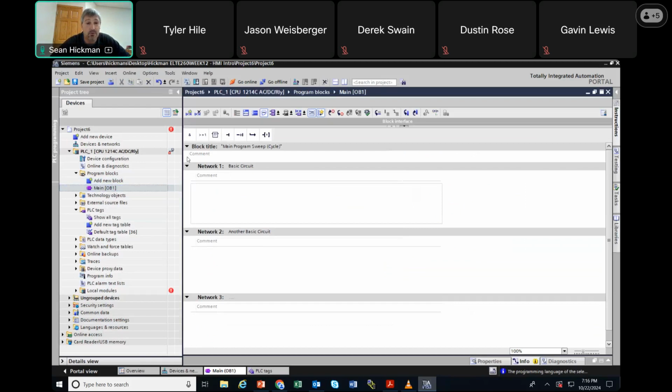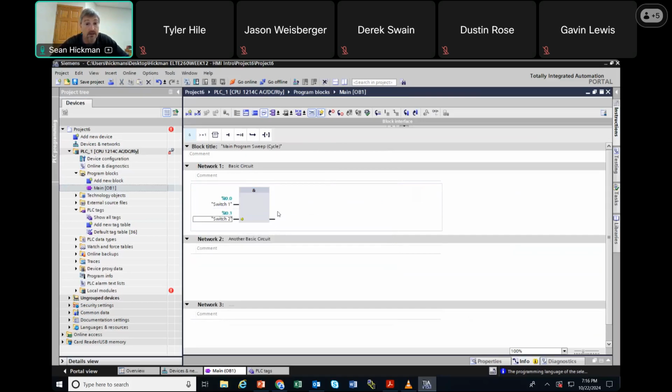So when you do function block programming, your instruction set changes. And if you hover over them, it says AND, okay? And so if I want an AND, I can just drag that in there, and it shows me an AND. And what would my AND be? Once again, I just type switch 1, because I already generated it. If I came here and typed switch 2, I generated it. And then I need to get an output on there. My output is right here. My assignment, I would set that there. And I could do my light 1, okay? And that's an AND.